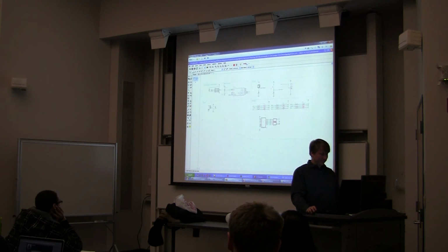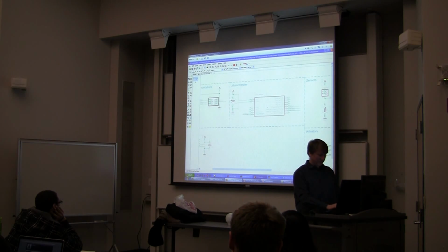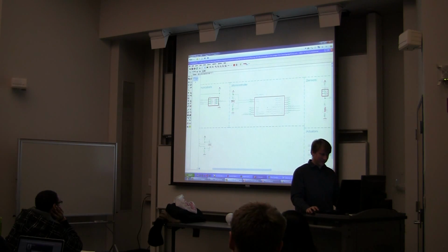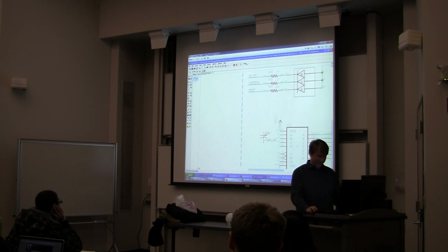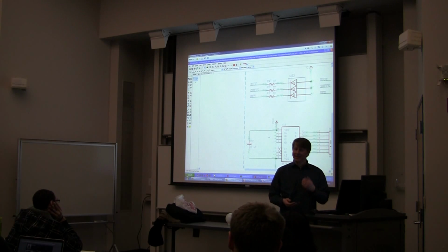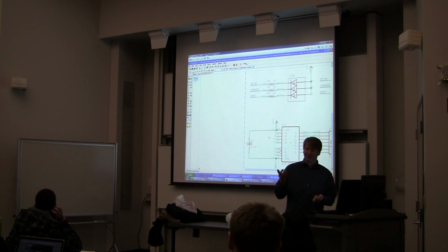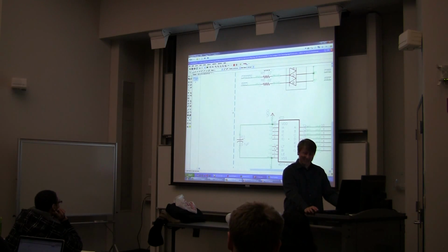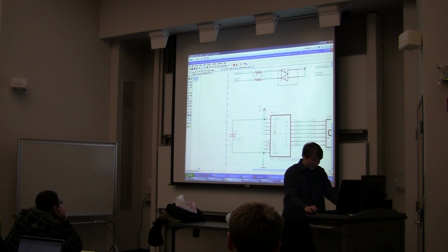Now, something I don't think we've sort of beaten into your brain, but anytime you have any sort of intelligent chip with legs, you need to put your own decoupling capacitor on its power supply. So I'm going to do that right now. So not optional. It sort of keeps your things from crashing. It's very frustrating to debug why your thing works when you display 0 through 7, but as soon as you try to display an 8 or a 9, your whole device resets. No one wants to have to figure that out, especially when it turns out putting like a little part fixes it.